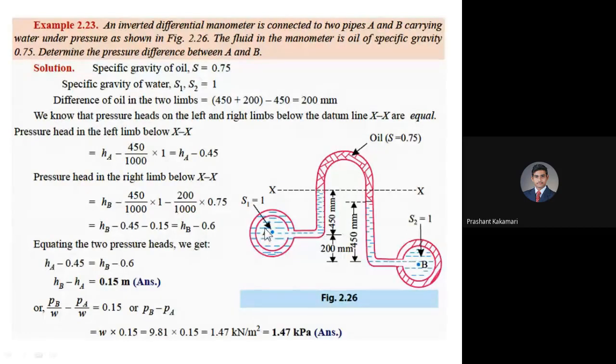So here on pipe A, pressure is more as per this. This is trying to push upwards. So when liquid moves above or rises with respect to PA, we are considering PA minus this liquid head. On the other side, what we are doing, PB, these liquid columns again are towards PB. We are taking minus of these two heads. Or you can take PB minus the water head minus the oil head. Is that clear?